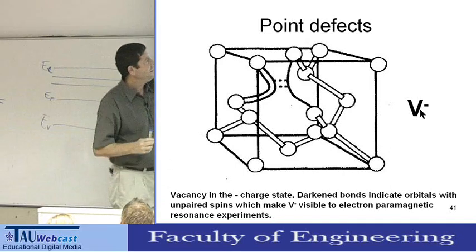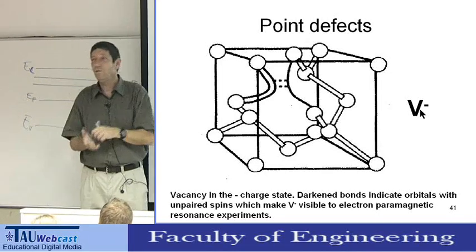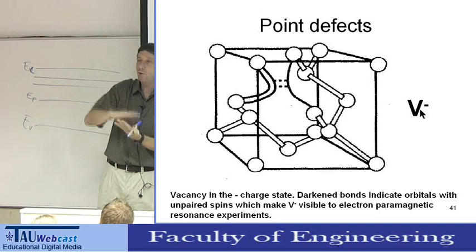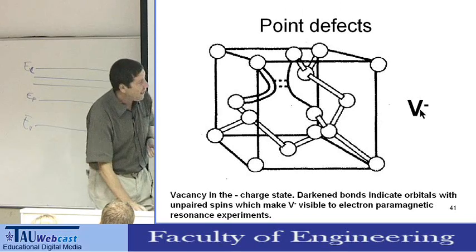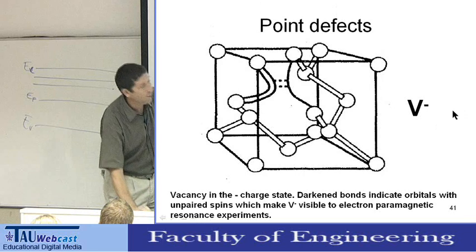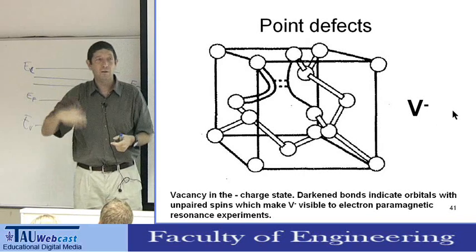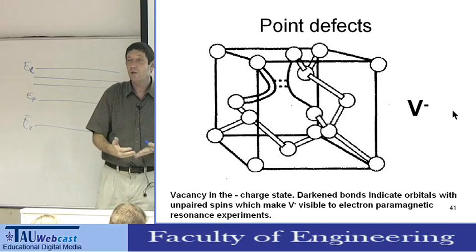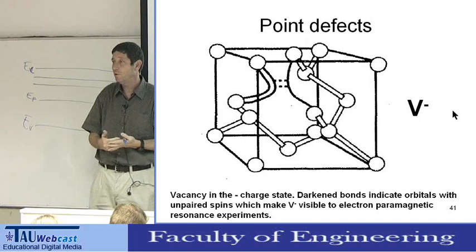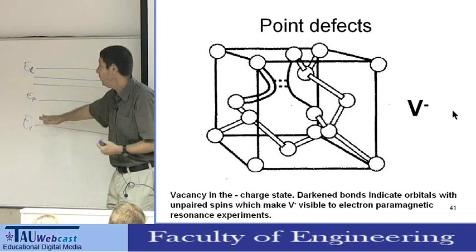So these vacancies will have electrons which are full if their energy is below the Fermi level, or depends on the doping. So if we have n-type doping, in n-type doping the Fermi level is high. In n-type doping the vacancies will be either 0 or they will be charged. They will be full with electrons. If we have p-type doping, then the Fermi level is low.